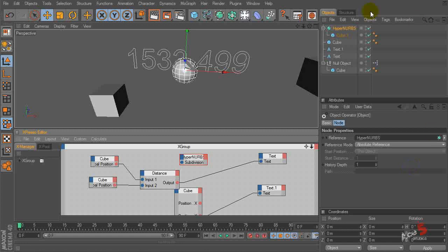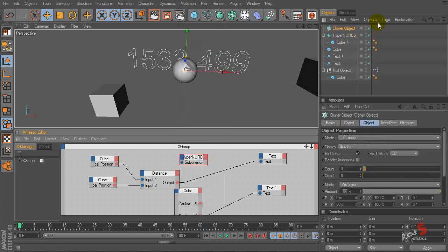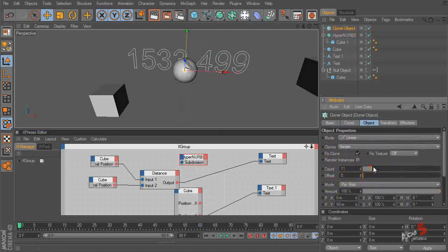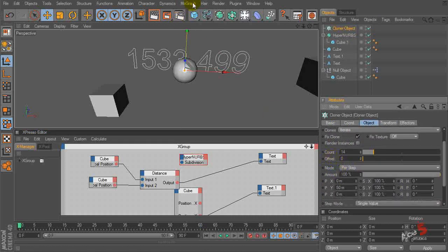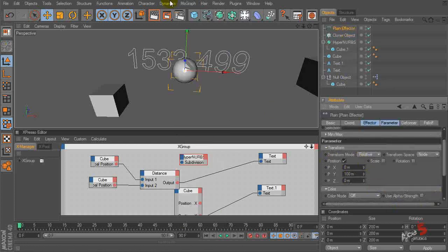Everything, like, you go to your MoGraph module and you have your cloner object, and this all has parameters, like numbers, counts, offsets, and even the effectors. You plug in, for example, your plane effector or your random effector, and you can feed all this information into each other to build these intricate webs of dependencies between objects. Most of it just really requires a range mapper.